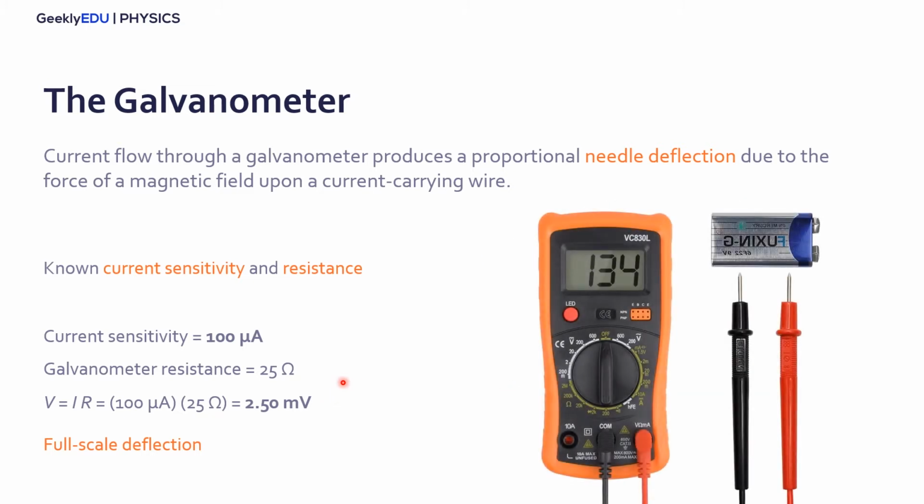So for the multimeter, we have a current sensitivity inside here, okay? And depending on where you put the switch, you're actually changing the resistance of the galvanometer. It has a lot of resistance inside here, and by changing the switch, we're putting different resistance inside. So we change the scale and we can measure the voltage or the current in very different circuits, or in a battery, for example, okay? So now let's dive in and see how the voltmeter and the ammeter work in a circuit.